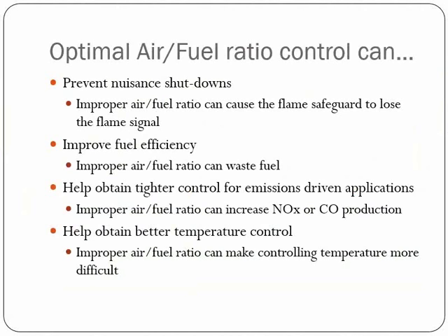In my time at Maxon, we did a lot of work with low NOx burners, and they typically ran with excess air somewhere in the 30 to 50% region.